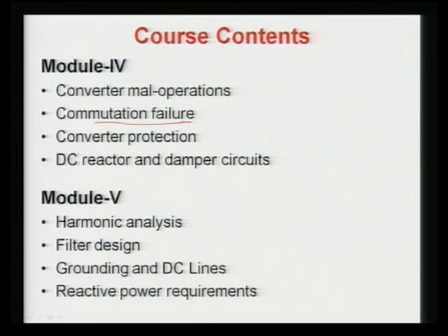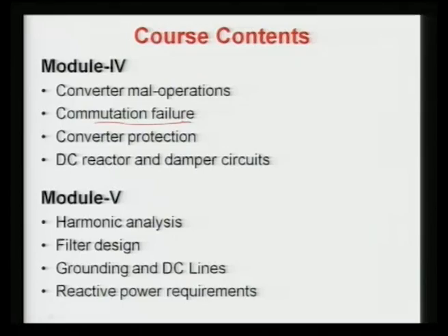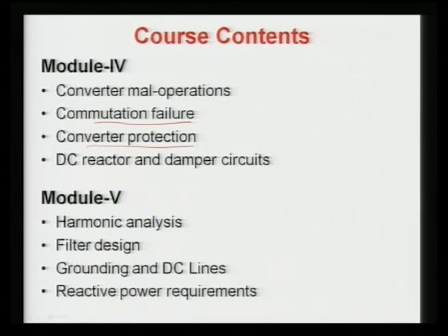The commutation failure, which occurs only on your inverter side, is a very frequent phenomenon. It is discussed again in detail for single commutation failure and double commutation failure. Single commutation failure means only one commutation failure in one cycle. If it happens more than once, it is called multiple commutation failure. So, in this module the first and second commutation failures are discussed, and we will see what the output voltages will be and what the impact on the valve voltages will be, etc.